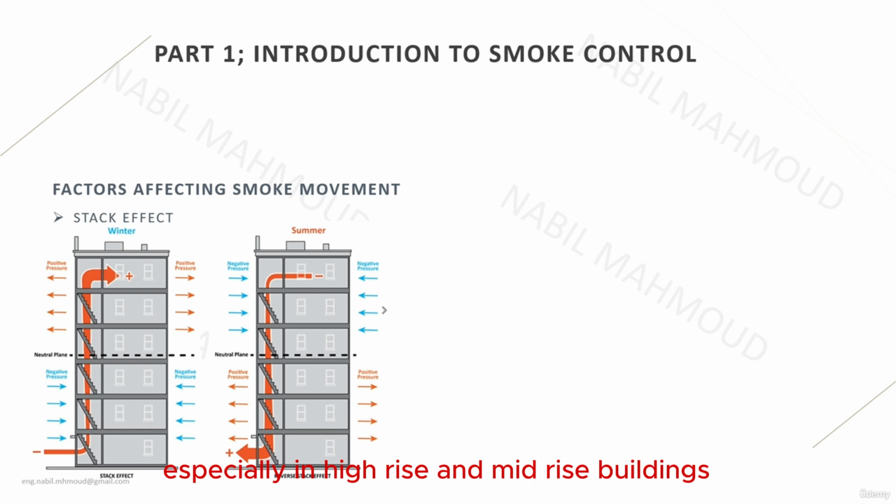and mid-rise buildings. If it's hot and humid outside, but it is cooled and air-conditioned inside, smoke will initially flow up, but then it will start migrating downward. This is due to the fact that the cold air inside the building has a relatively higher density than the hot air outside the building. So the air in the top floors will start to flow down, and it will exit from the low areas inside the building, and this will be compensated by cold air from the upper floors again.